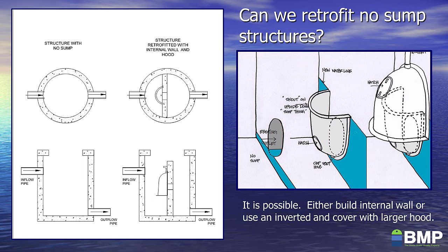In either case, your sump depth is going to be limited by either the orifice invert or the top of the inverted snout, and you're not going to have a lot of volume to capture your collected materials. So keep that in mind. You will want to maintain a structure that has a retrofitted sump much more often than a normal structure would be.